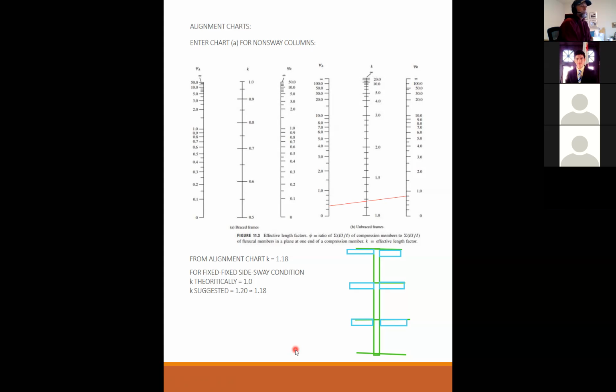Technically speaking, when I design this column, I am actually designing 3 columns. This column is a different design than this column, a different design than this column. Even though this is all one continuous piece of concrete, or even if it's precast, it literally is one piece of concrete, design-wise it's 3 independent columns. And if this is braced or unbraced, either way, you're going to get a different effective length here than you have here, because this is a different support condition than this is.